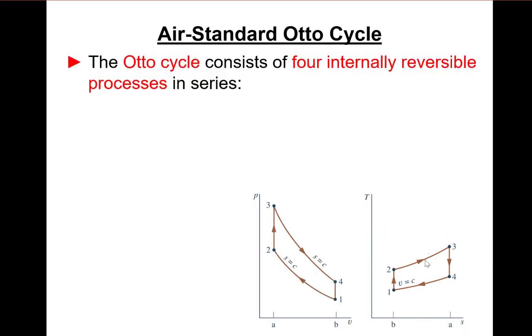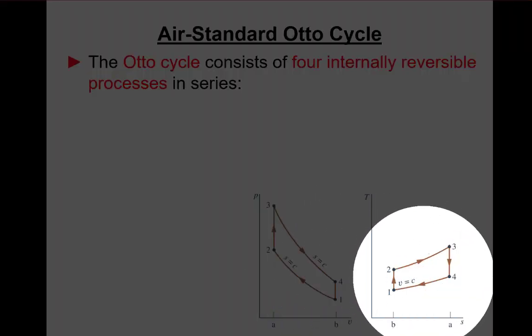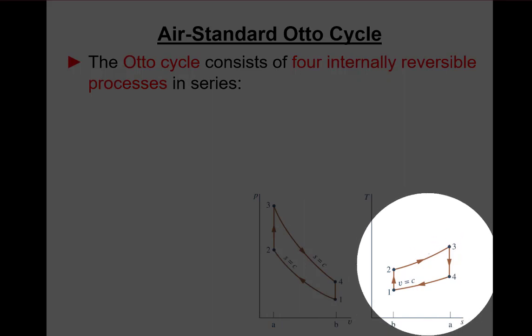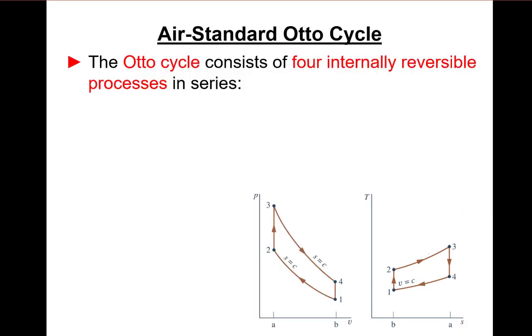So the nice thing about PV diagrams, remember on a PV diagram, we can tell something about work, right? Because work is the integral of P dV. But on a TS diagram, it's nice because we can easily find these isentropic processes, which I'm saying are kind of the key to unlock how to solve these problems, right?